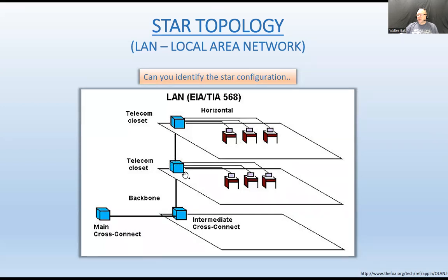So if there is a communication closet or a LAN room on this floor, quite often, almost always, you're going to find that another communication closet or a LAN room for the floor below is going to be directly below that one. It makes things so much easier for installing things and running the communication wiring and whatnot. So over here, this would be considered a riser. And it will also be part of the backbone.